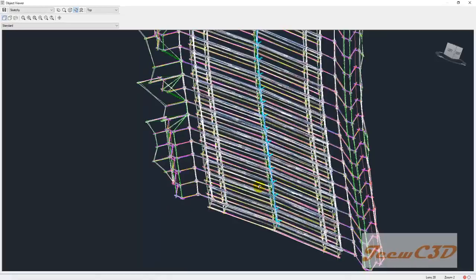You can see the cross sections are applied at 10 meter intervals. We will be connecting the top points of the cross sections for the assemblies, and we are creating the plane connecting all those top points. So that plane is called a corridor surface. We call it the corridor top surface, the surface which is created by connecting the top points of the corridor.